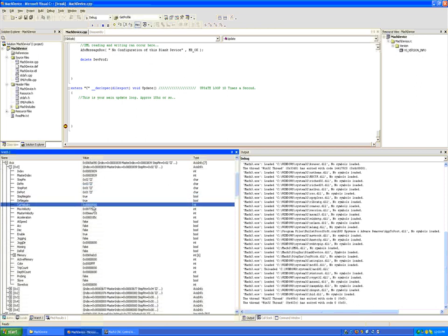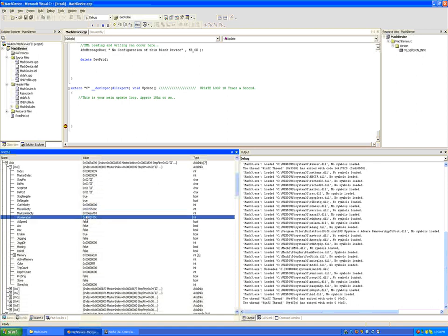Current velocity of an axis is always stored as the program runs. Maximum velocity is a clip variable, which stops us from jogging too fast if we're jogging. We have a master velocity, master velocity is a clip variable. Max velocity tells the system if I was to start to jog right at the moment, this is the maximum speed it is allowed to accelerate to using this acceleration variable.